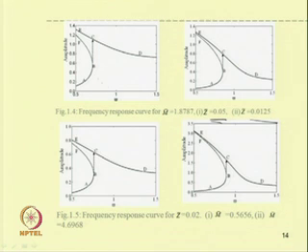One can see this position, this is B. With a higher value of excitation, this position shifts to the left. So, at a lower value of omega, the system will have a jump up phenomenon, but for a system with less value of Z, that is the amplitude of base excitation.